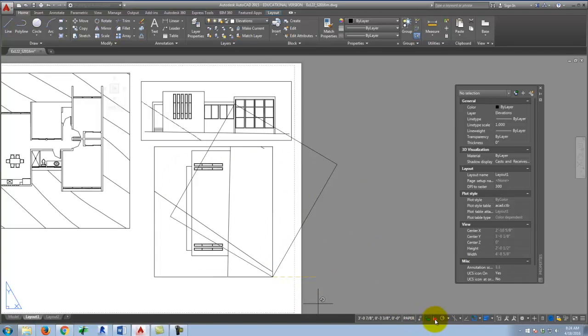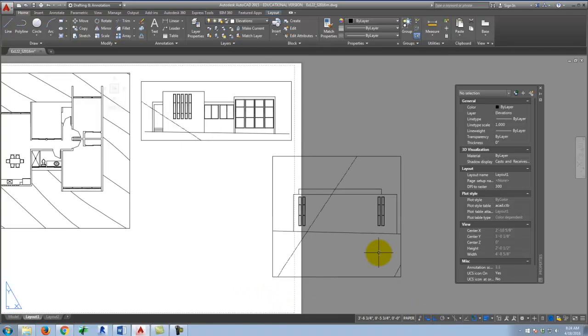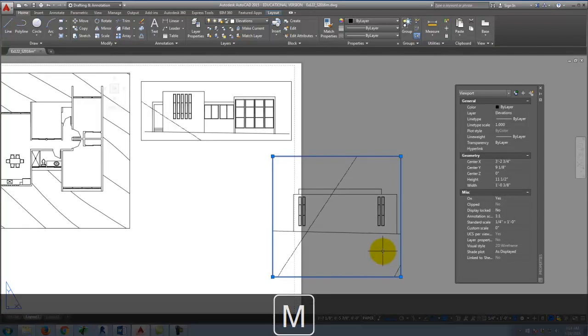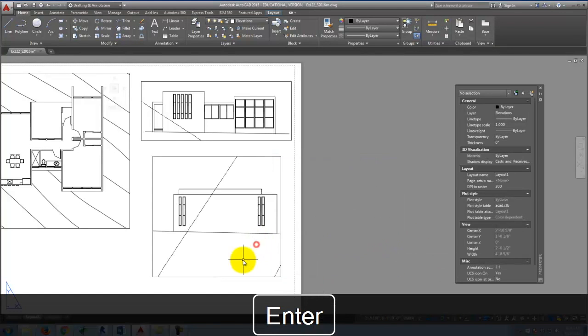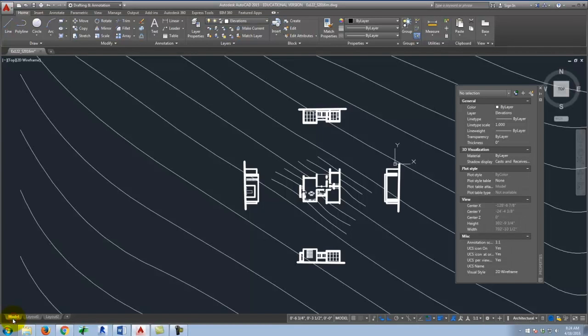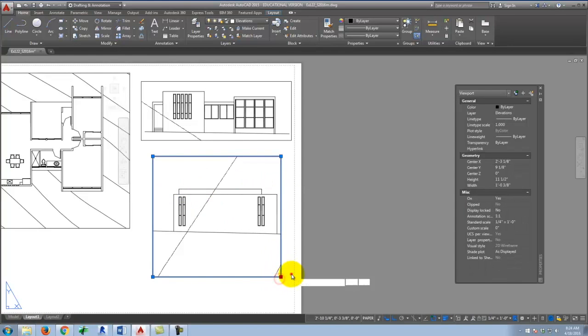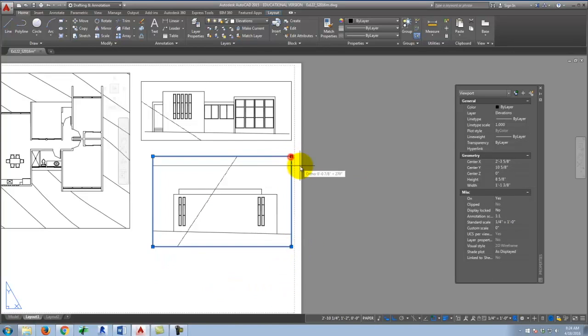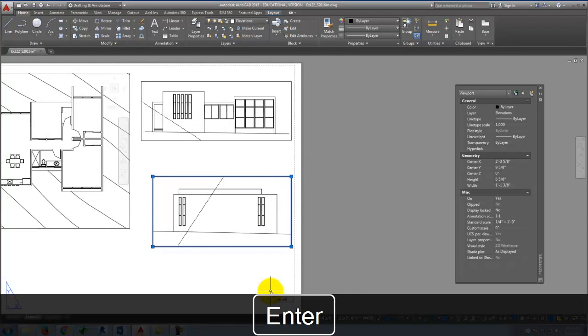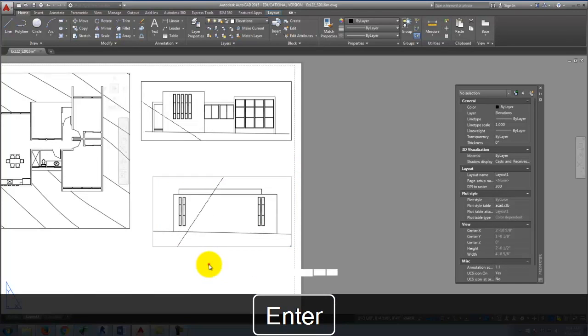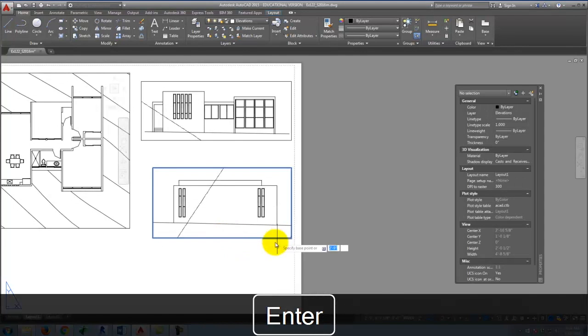object. Let me turn on ortho here for a second. And I can rotate it over to the side. Even though I drew this object sideways in Modelspace, when it comes to the layout view, I can correct it and have it oriented in the correct manner. That's one of the really good, powerful things about viewports, is that we can customize and choose which rotation this particular piece is going to be. So I've now created the second view, or the second elevation. Let me go ahead and move this.